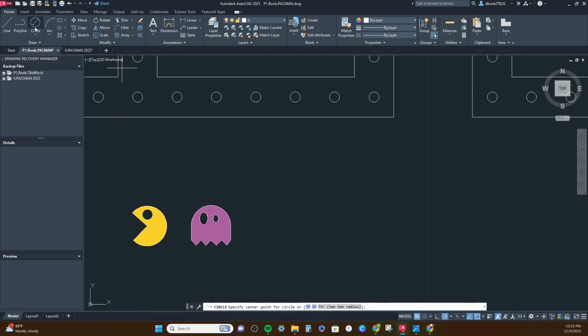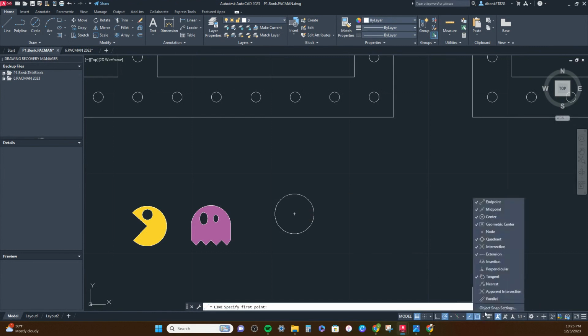You're going to go to the circle, center diameter circle tool. As you start drawing the circle, it's a 1/4 inch circle. So 1/4, enter is what you're going to do. Make the mouth by going to the center. Actually, before we get going any further with this, go into the object snaps and make sure quadrant is on and tangent is on, in addition to the other ones that we've had turned on. I find all of them useful and important. So this is just my way.